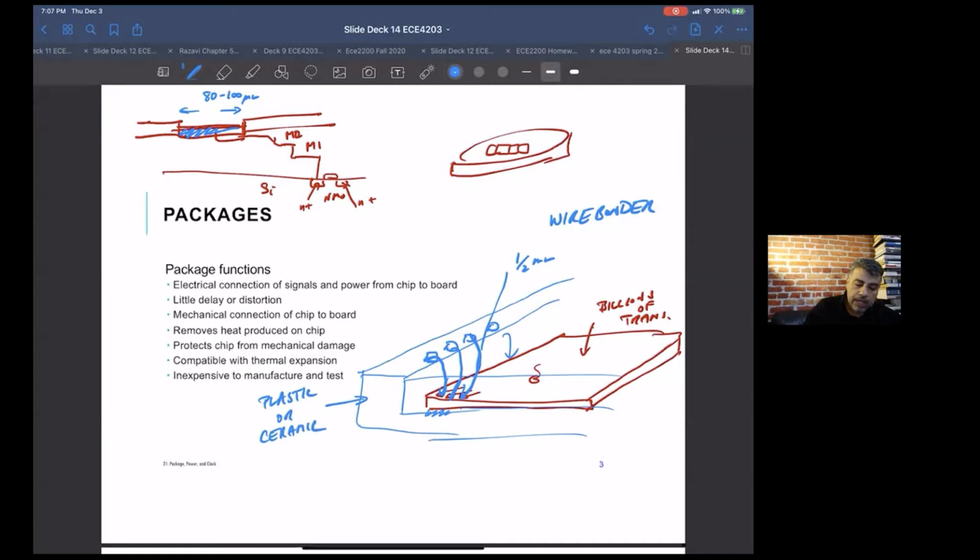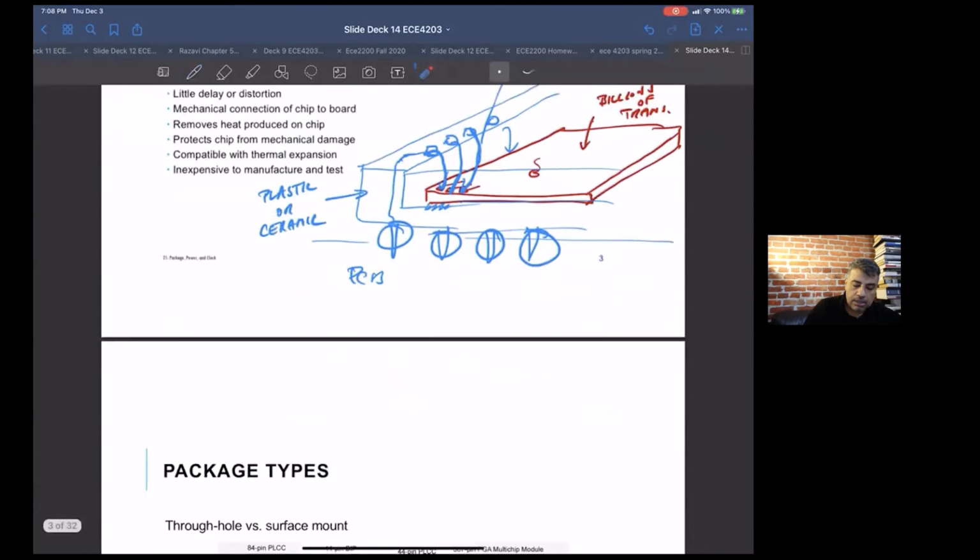Typically the case, okay? And then inside this plastic package, it's easier to think of it in terms of a plastic. You've got its own connections that come out to what you typically see is a bunch of pins that then go into your printed circuit board, or you'll see ball bonds in the more advanced. You might not see the ball bonds because they're kind of underneath the package, but basically the idea is you are connecting these relatively small 80 to 100 micron pads. You can't really work with an 80 or 100 micron thing. You're basically electrically connecting those to a pin that you see in your package, like sort of an old